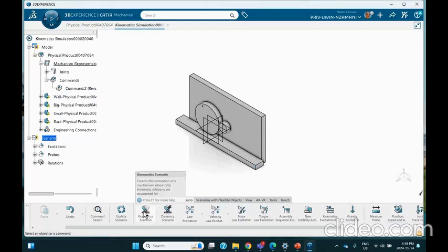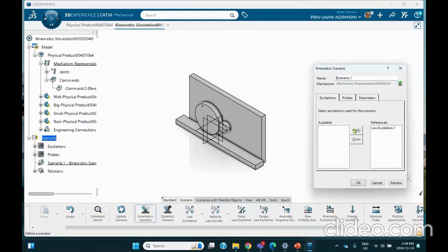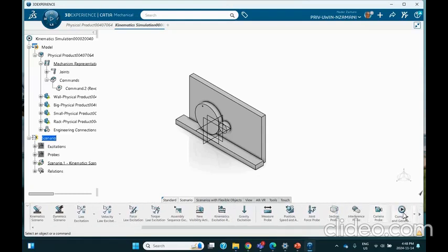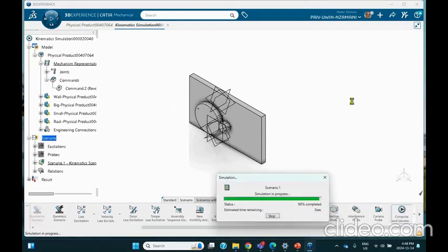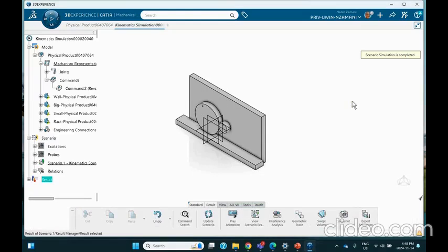Now we go create a kinematic scenario. There is a law, the formula for 180 RPM, and there is the probe that I created. Let's do it over a 2-second interval, because 180 RPM means 3 turns in each second. So let's do it over three seconds. If necessary, we're going to fix this. 0.05, and say okay. And we're going to run it. It went too far, but that's okay. No problem. So let's go ahead and plot this.